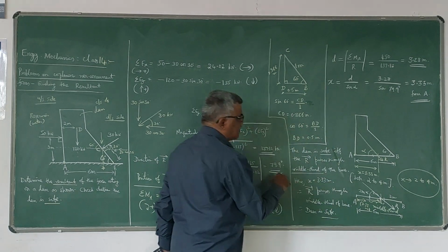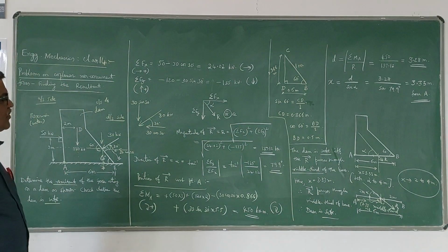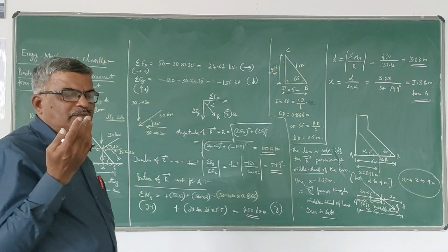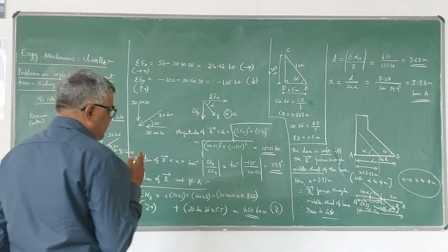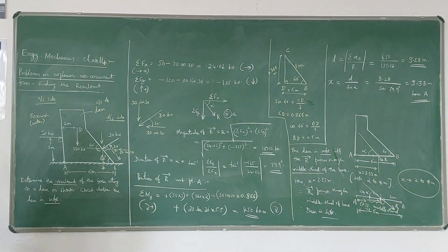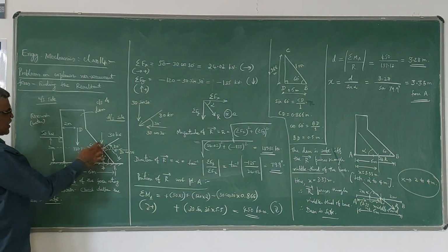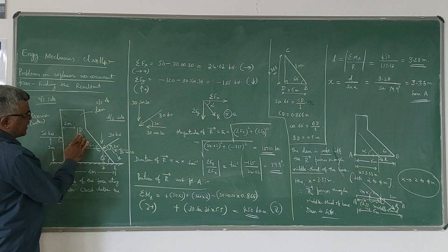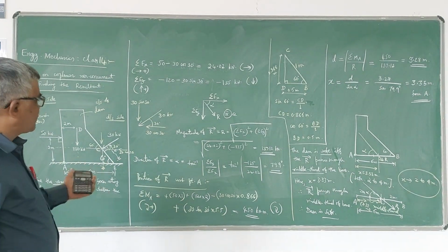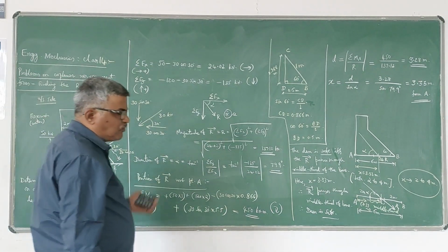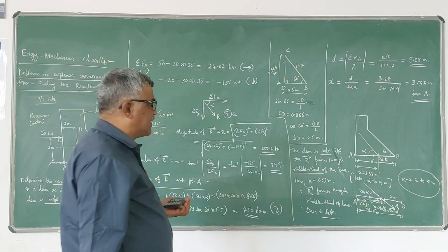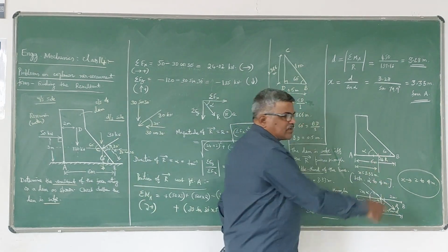So this is how they can. This is a practical problem, wherein he will give the forces acting on a dam. Of course, it's a very simple dam, an urban dam. Normally, in dams you have different types. A gravity dam will have huge heights. Whereas this is a small urban dam where the base width given is 6 meters and only 3 forces are given. One is water force, another is self-weight, another one is the weight of water on the other side. So by giving 3 forces, we have calculated the resultant, and we have to find the x-intercept of the resultant. If the x-intercept of the resultant falls in the middle third of the base, then we can say the dam is safe.